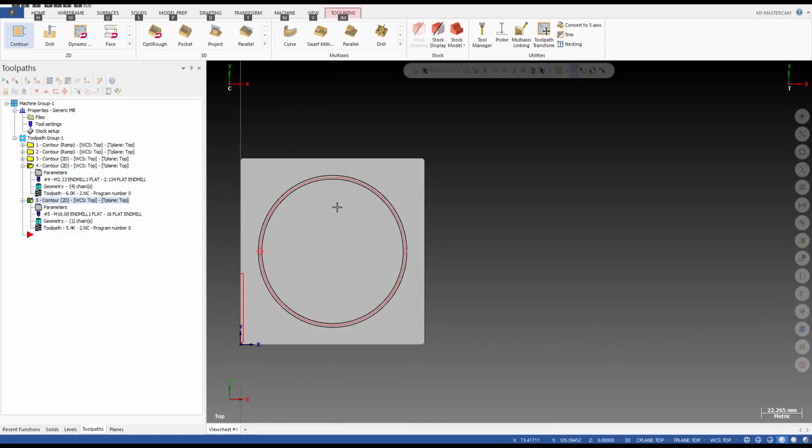summary. In this video, I just show you we have three methods to create a custom profile tool, but in this video I just focus on the first and the third method. The first method, we draw the tool profile and store that on a level, and after that when we create a custom tool we will link the geometry from that level to the tool profile. And the second method is we use an external step file.